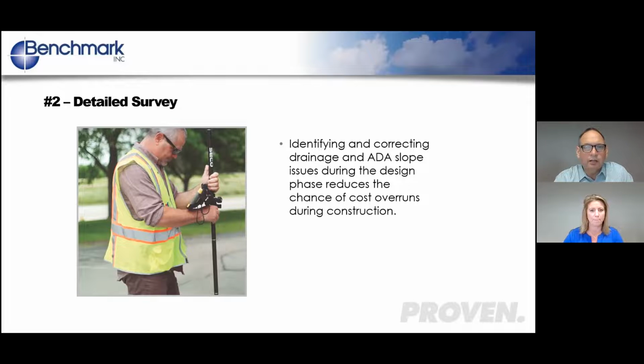Elise, a good example of why it's important to have a survey done to know the grades of your parking lot and know that the water drains is, I've seen it more than once where the contractor will start the project, especially with overlays, and they'll get to a spot where they don't think the drainage is going to work or it's going to be tight, and they go to the owner looking for a change order to correct those drainage areas. Or worse, they ask the owner to sign off that if there's a puddle in that area or it doesn't drain properly, the contractor is not responsible. So that's why it's really important to make sure that the drainage works on the site before you start your paving project. Yeah, great points, Troy.